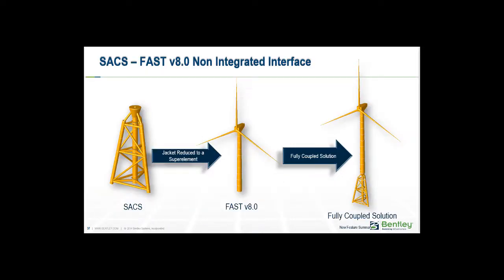The process in this case is that initially we take the jacket model and we reduce it to a super element and connect it to the bottom of the tower. Then we do a fully coupled solution.